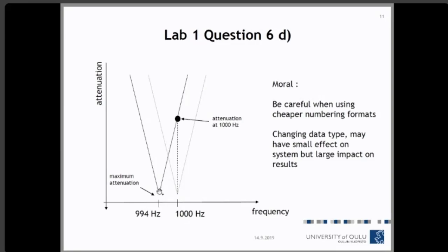don't show very precise attenuation. They attenuate the signal that resides on the 994 hertz bin, if I remember correctly. The 32-bit floating point and the 32-bit fixed point integer with the scaling factor that was chosen in the lab performed fine, and the worst result was from the 16-bit floating point.